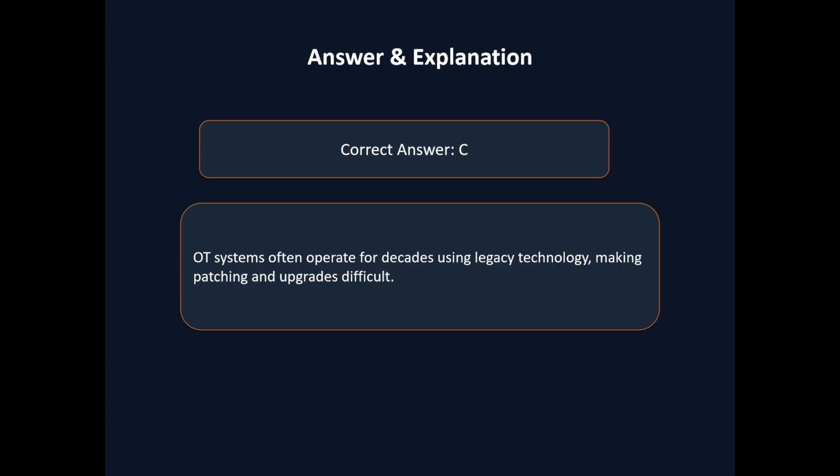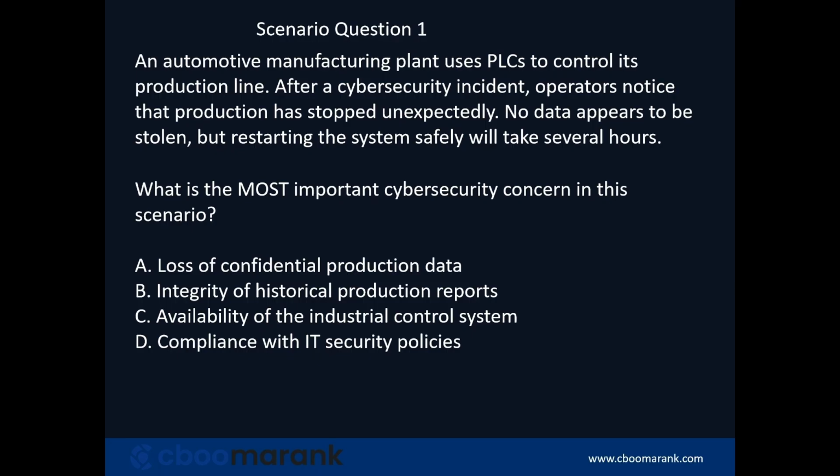Many OT systems operate for decades. I think we have already seen from 10 to 30 years without any updates, since they are designed before cybersecurity is even a major concern, because patching and upgrading these systems can be risky or disruptive. Vulnerabilities often remain in place for a long period of time due to this long life cycle and legacy technology.